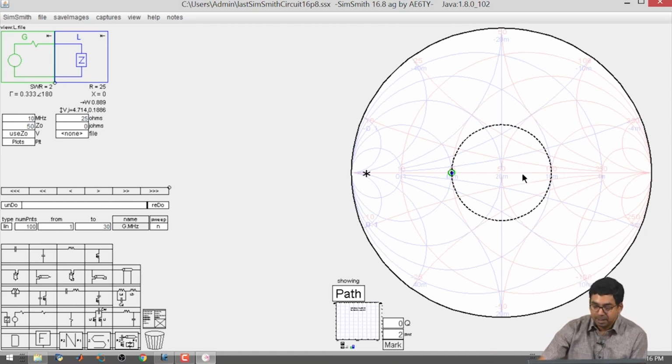Now, once I have this, the question that can be asked is, how do I make the impedance as seen from the input side? The generating side is over here, and looking in this direction it should be 50 ohms, so that I do not get 0.889 watts as shown over here, but I get the entire 1 watt. This is the objective of impedance matching.